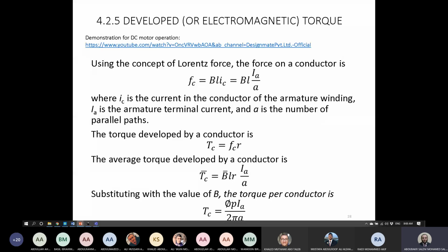In the case of a generator, we can say that it's rectification because the EMF inside the coils will be AC, so we convert it to DC outside the machine. However, in motoring mode, we convert the DC input voltage and current to make a rotating AC EMF or rotating flux in order to rotate the machine.